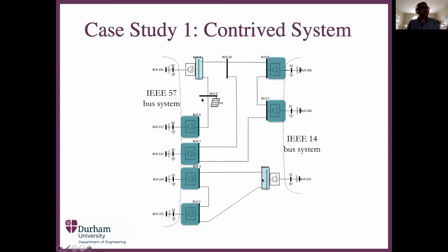So they are able to maintain a fixed voltage in the DC network, and there are 2 distinct multi-terminal DC networks. This one is not connected to this one. So this converter maintains the voltage here, and you're able to schedule the power as you see fit using these 2 converters.